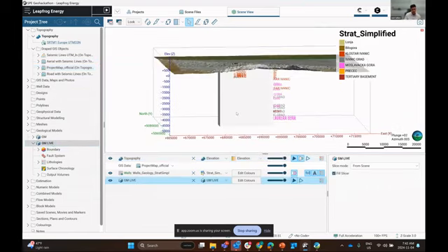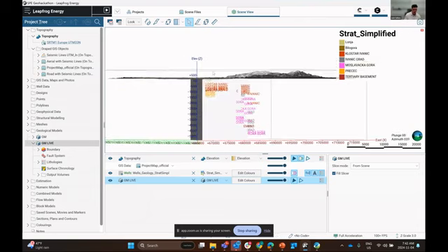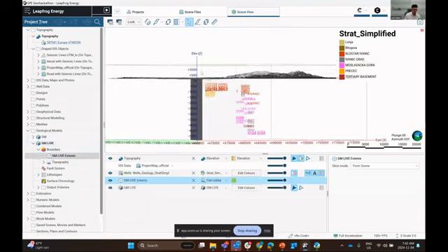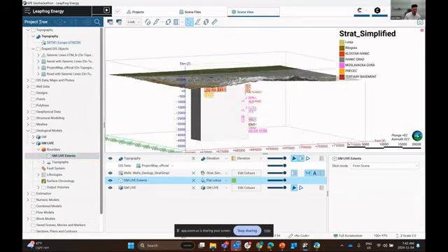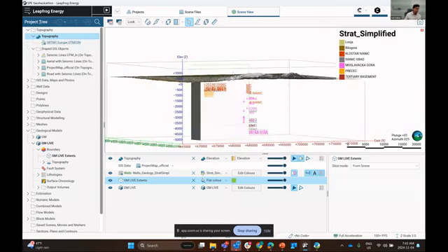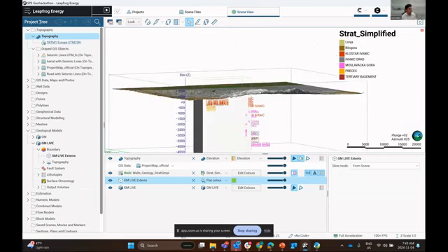So you're probably wondering why the extents of our geologic model actually extended above topography. So although the boundary, if we expand out this geologic model, we can look right here, the boundary extends above topography. The topography, the surface that's in this topography folder, is a special surface. This surface acts as the air-earth interface. So it essentially clips anything that is above topography from this particular geologic model. And you'll notice that that's consistent with the majority of objects that you're going to be creating.